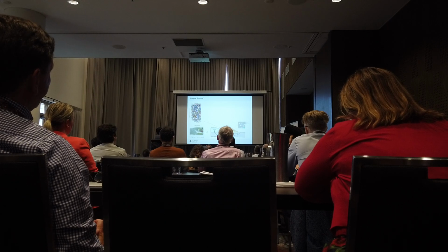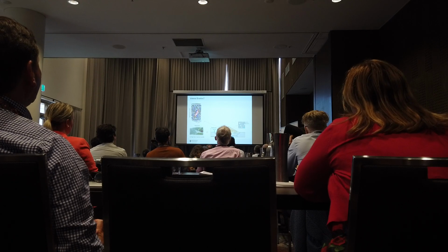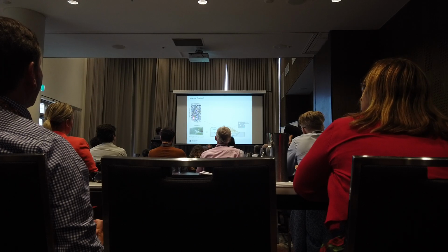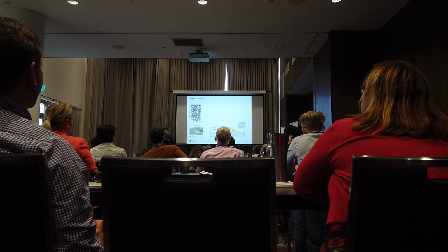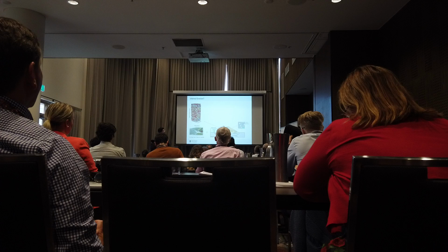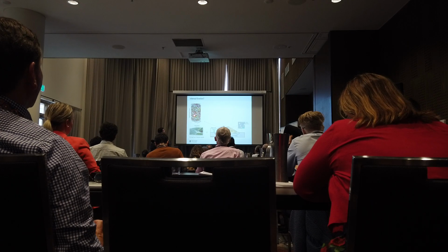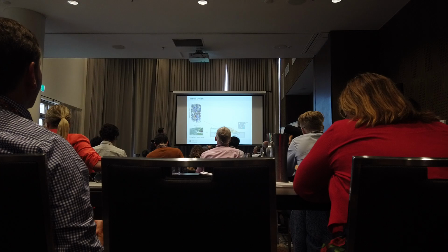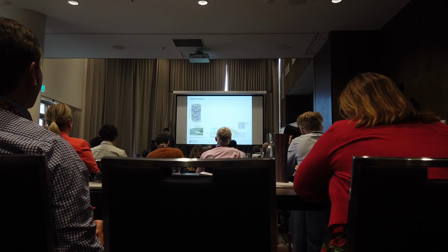This is the CFD-DEM simulation showing how the fine particles are transported through the pores of the large grains due to the seepage flows. And this is an example of internal erosion. And you can see this internal erosion basically occurs at a very small scale.